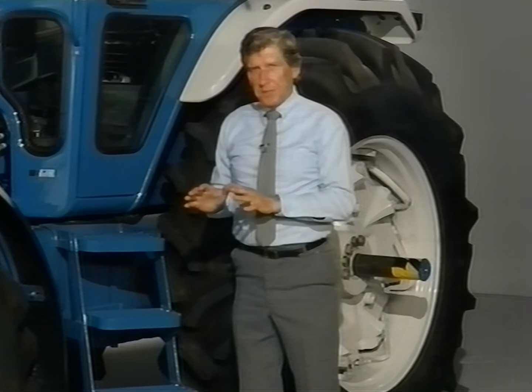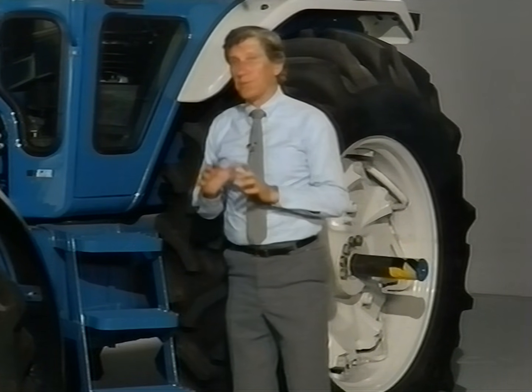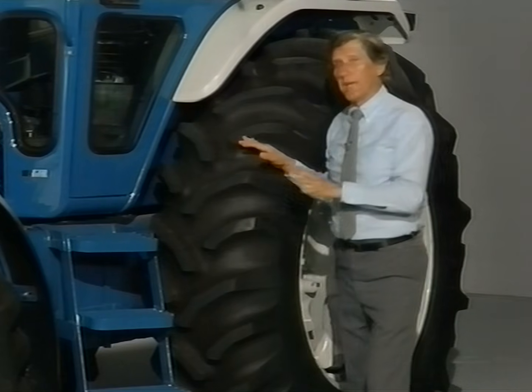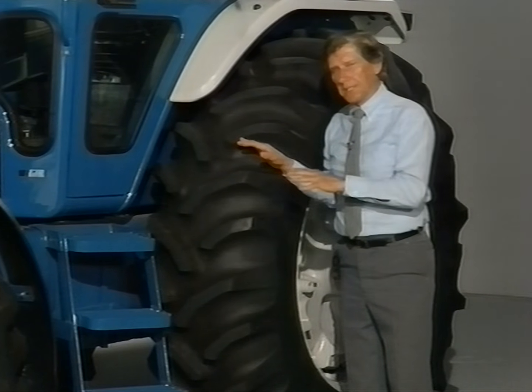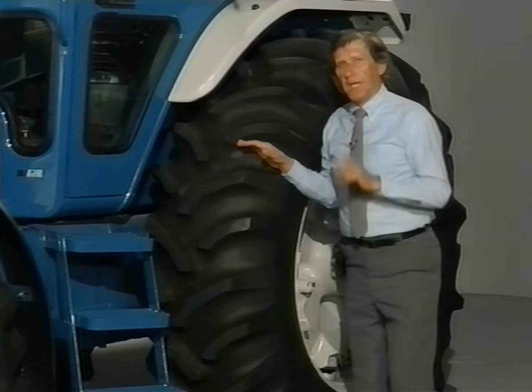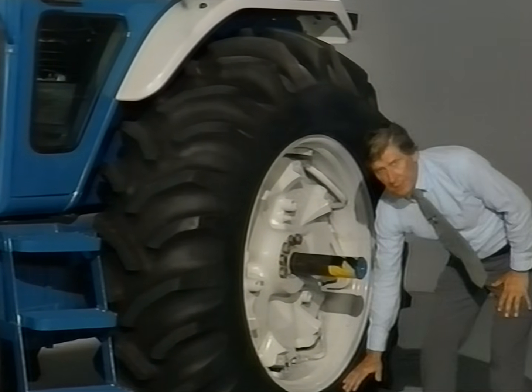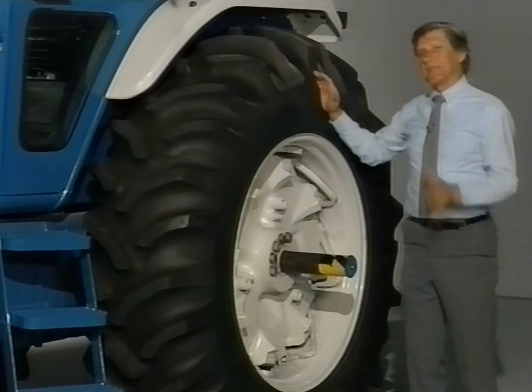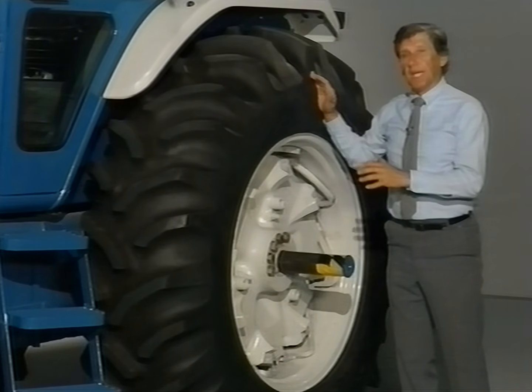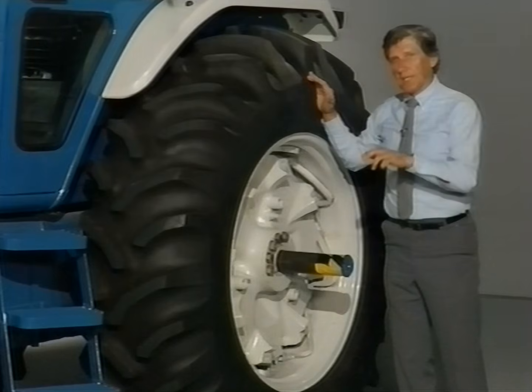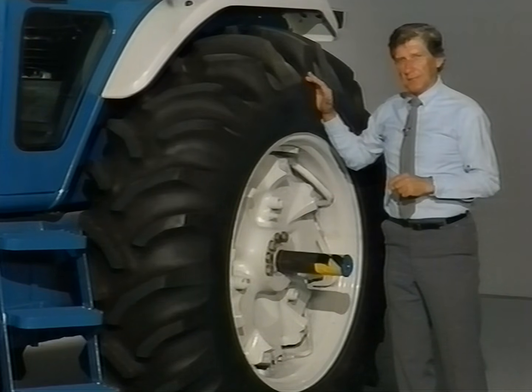Calibrating the electronic instrument panel to display the correct ground speed is necessary if replacement tyres are more than 1/2 inch different in rolling radius from the original tyres. Calibrating the EIP is a matter of finding the rolling radius of the rear tyres, matching that radius with a calibration number, and entering that number in the electronic instrument panel's memory.